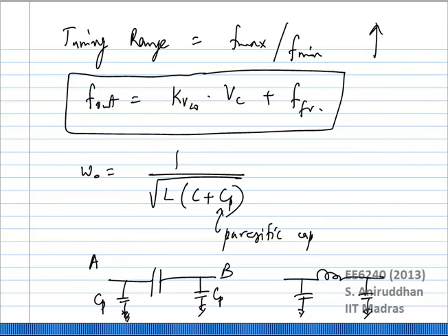And we said this is actually a voltage controlled oscillator, not just a standalone oscillator, which means instead of just letting it run by itself, you are going to run it inside a PLL, okay, where the PLL feedback sets the control voltage and therefore sets the frequency of the oscillator. And you want the behavior to be linear to place it in the PLL.